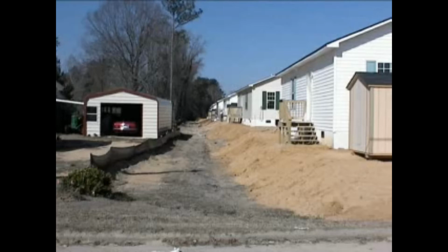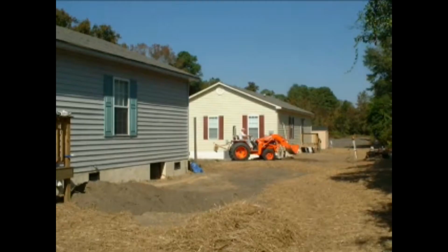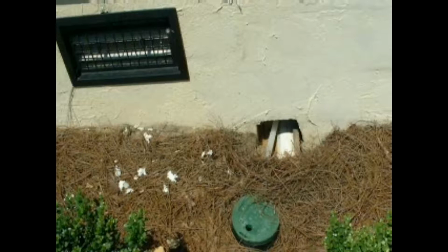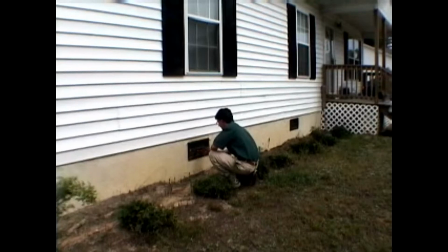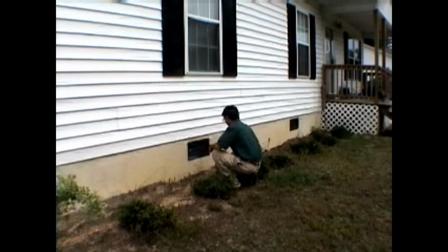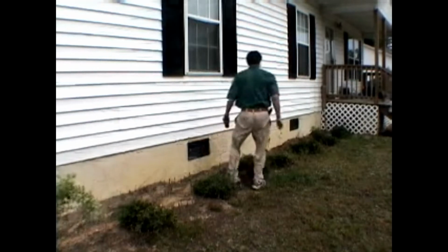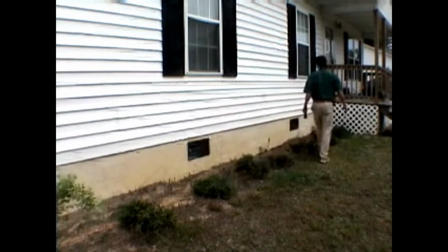During the experiment setup, all crawlspace related moisture issues were resolved. These efforts included correcting construction, grading, and drainage problems, sealing any foundation holes that could allow water entry, and fixing plumbing leaks. The crawl spaces in these test homes average about 2 feet high, and virtually all of the wall area in the crawl space is above grade. Ten standard size 8 by 16 inch foundation vents ventilate the crawl spaces.